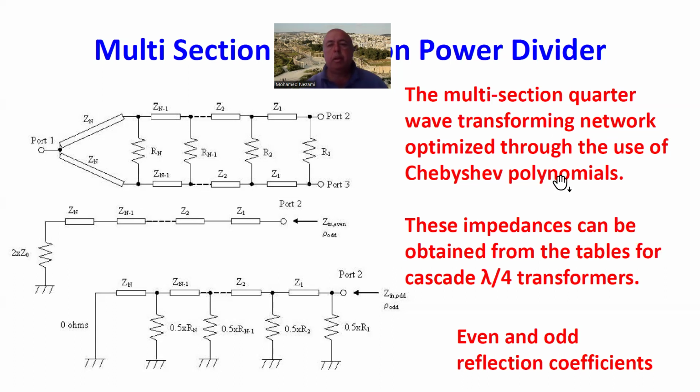And then, like I mentioned before, when we took a graduate course, master's degree level, we usually derived this, but now practically we just resort to tables and to computer-aided design apps that are available from various sources. The one I'm going to use today is available freely from Microwave 101, and I'll show you, and it works very well. It's based on the Chebyshev polynomials.